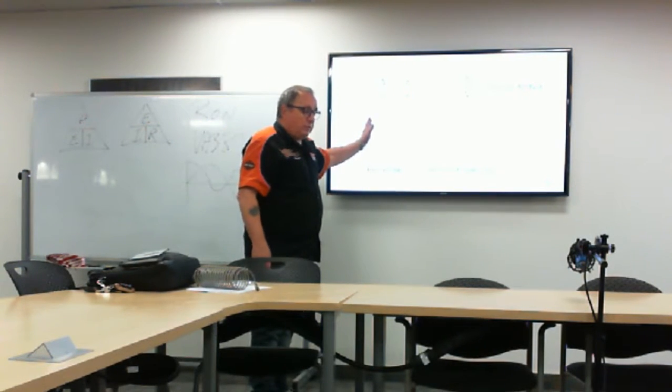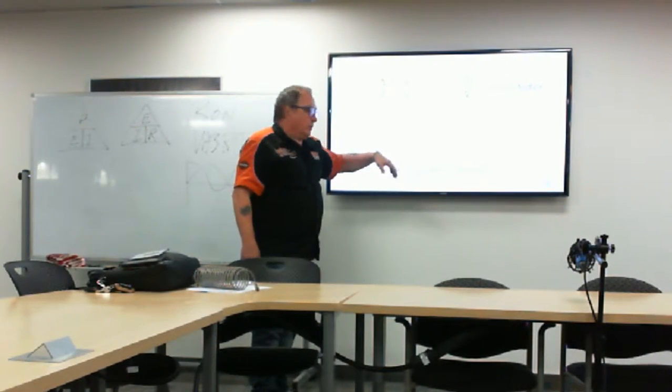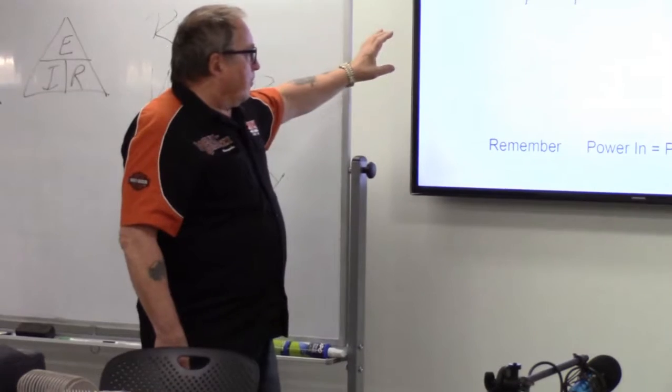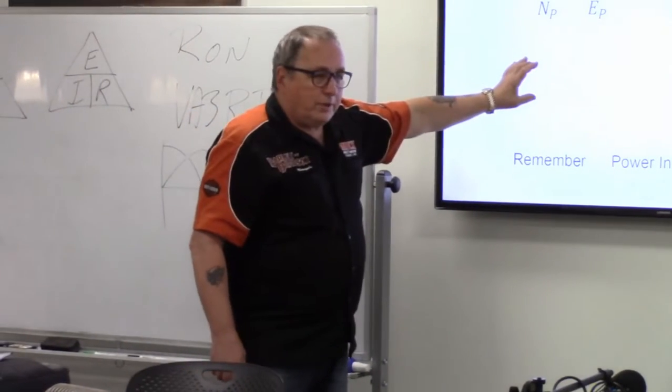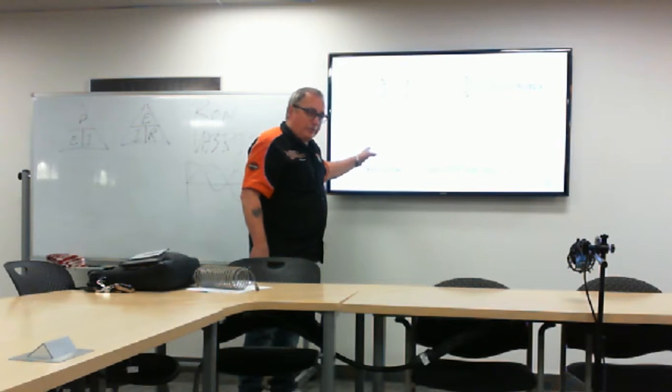A step-up transformer would have 10 turns on the primary and 100 turns on the secondary, so that I put 10 volts in here, I get 100 volts out there. But again, I only get 1 amp, and I have to use 10 amps to get that 1 amp.